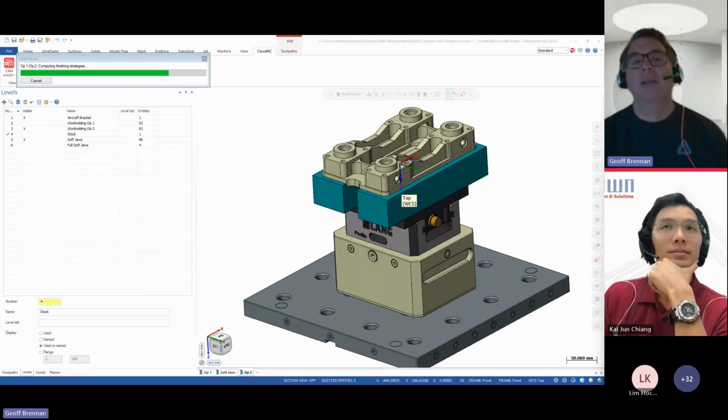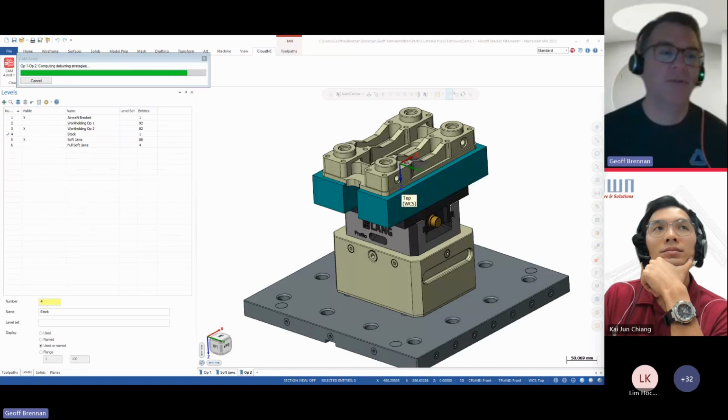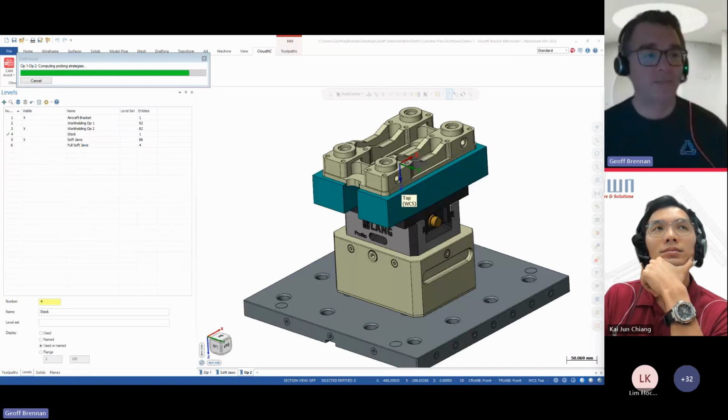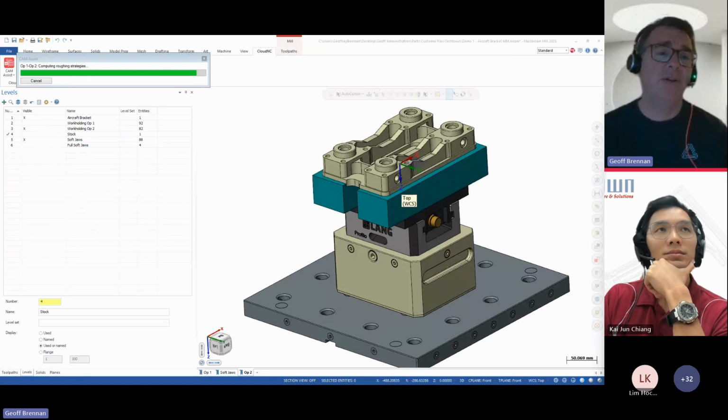Currently, we're doing a bit of hard coding between Cam Assist and the tool manager with regards to materials. So if you need to run your own tool library, which of course you're going to, one of the things that we're getting customers to do now is basically copy the materials from one of those demo libraries back into their own library.